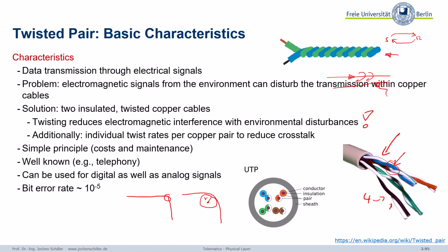If you make a real 90-degree corner, you can do this with the cable, but this will, so to speak, de-twist the cable internally, and this makes the whole cable more vulnerable to interference from the outside world. So this is not like a power cable, which you can bend as long as you don't break it. Here, nope, because we transmit higher frequencies, as we'll see.